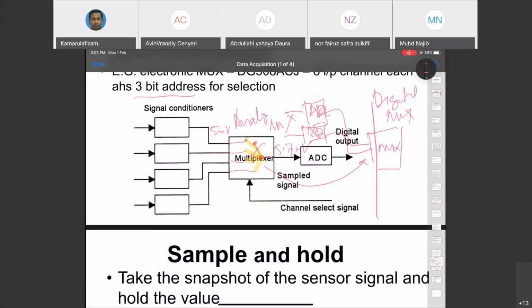Noise is a big issue. It's a big disturbance which you have to handle. If your system is running on a high voltage and you don't care about this small millivolt or nanovolt noise, maybe you don't mind putting the multiplexer on the analog side.